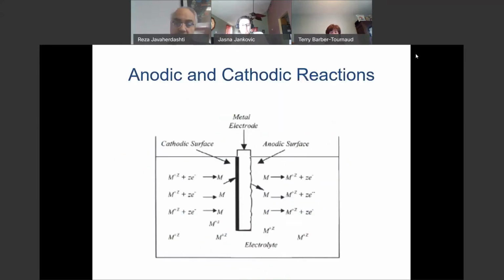What is corrosion? You have metal that when you put it into a corrosive environment, it starts to corrode. What does it mean? It means that when you have copper and, for example, iron, based on their potentials, they start to release and receive electrons. If they release electrons, that metal is called an anode, and if they receive electrons, that metal is called a cathode.